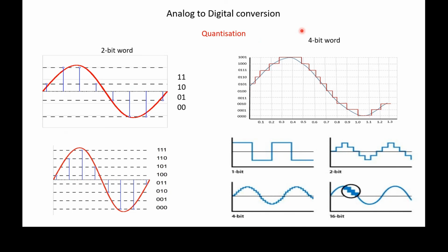The other thing that we have to be careful about is how we quantize the signal. And this is where we would have to either amplify or attenuate our signal so that its variation goes plus and minus or 0 to whatever the maximum is and fills the space of our analog converter, which goes from, say, -5 to +5.